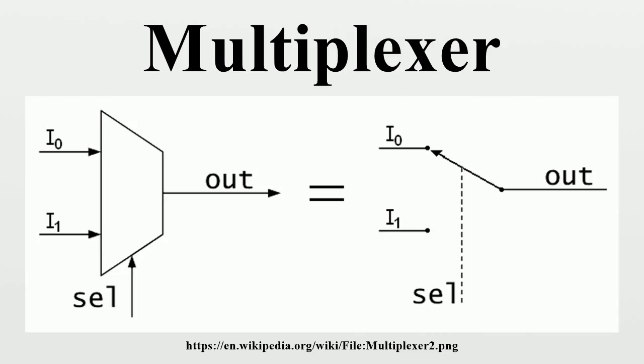Chaining multiplexers. Larger multiplexers can be constructed by using smaller multiplexers by chaining them together. For example, an 8-to-1 multiplexer can be made with two 4-to-1 and one 2-to-1 multiplexers. The two 4-to-1 multiplexer outputs are fed into the 2-to-1 with the selector pins on the 4-to-1s put in parallel, giving a total number of selector inputs of 3, which is equivalent to an 8-to-1. List of ICs which provide multiplexing. The 7400 series has several ICs that contain multiplexers.